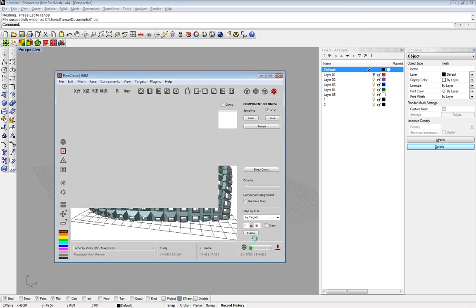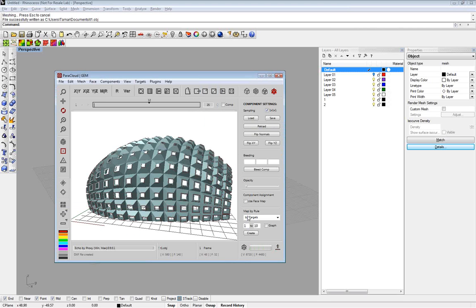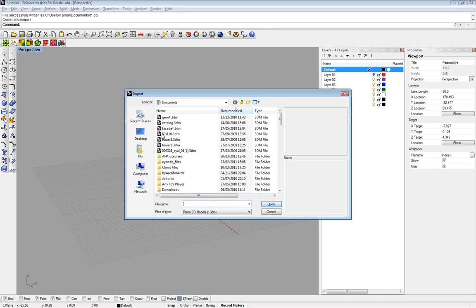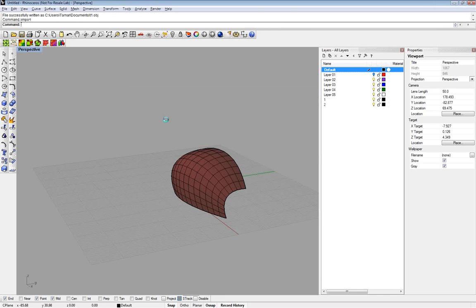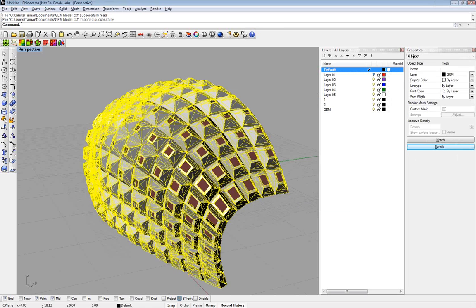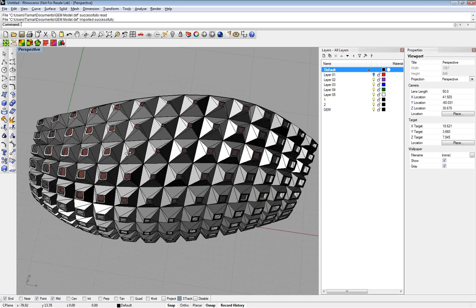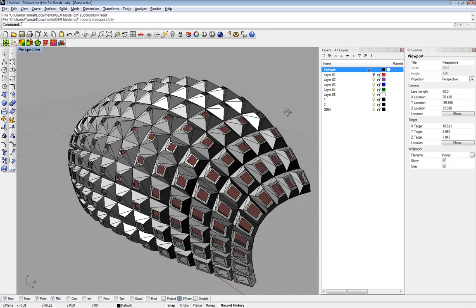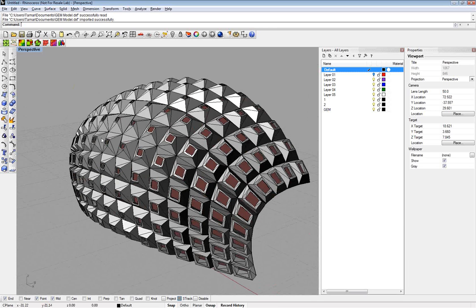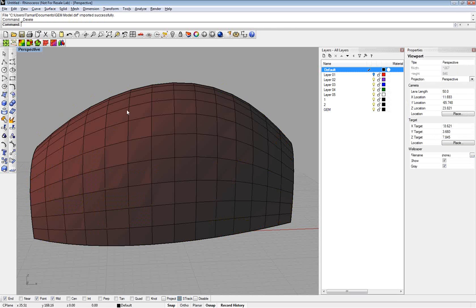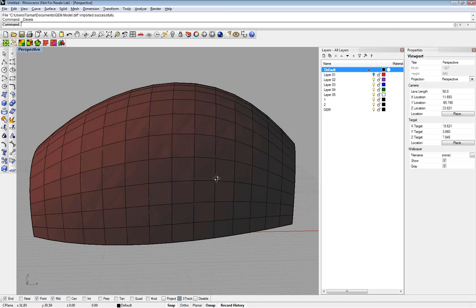Now, when I create an output from that, I can create the output in different formats, from DXF to Collada, STL, VRML, whatever I want, and bring that geometry in by simply importing it, calling the file I just created, and of course the geometry will be brought in. So I can find simple methods to control geometry this way, and there are many tools that we can work with, using random tools, directional tools, all kinds of effects that we wish to create on patterns, as well as controlling the different patterns of our design geometry.